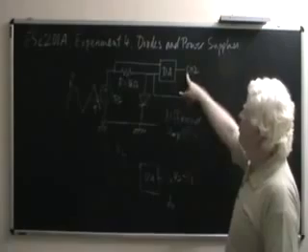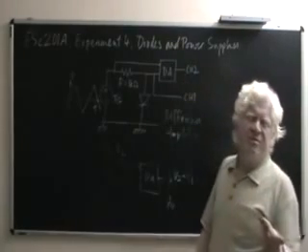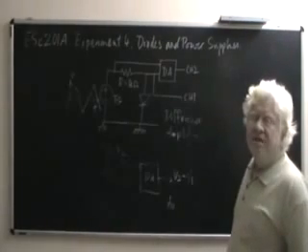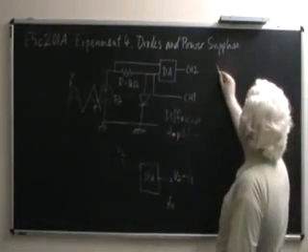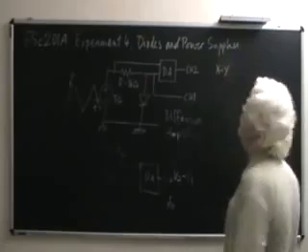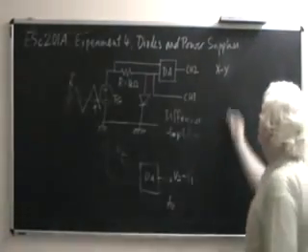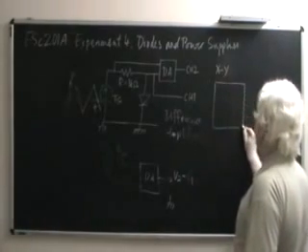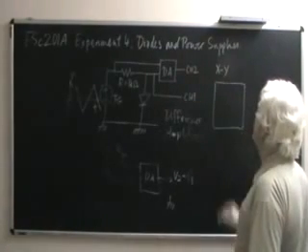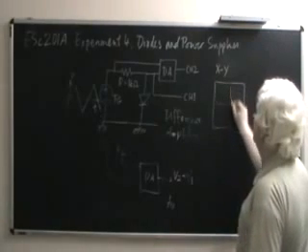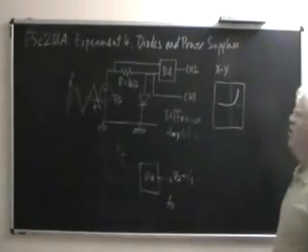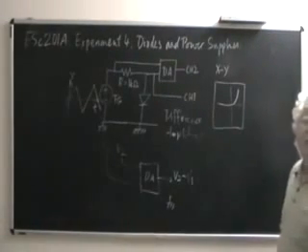So you can read off channel 2 in milliamperes. Channel 1 is read out in volts. Now if you put this oscilloscope in XY mode, something that you have already done in previous experiments, you would see a plot, after going through all the procedures of centering the dot and the screen, etc. You would see a plot that looks like this on your scope. This is what you would see.